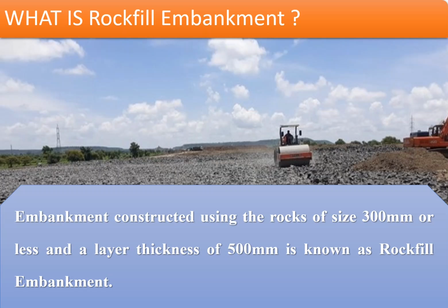Now coming to the Rockfill embankment. An embankment constructed using rocks of size 300 millimeters or less and a layer thickness of 500 millimeters instead of 250 millimeters, constructed to achieve the required FRL, is known as a Rockfill embankment.